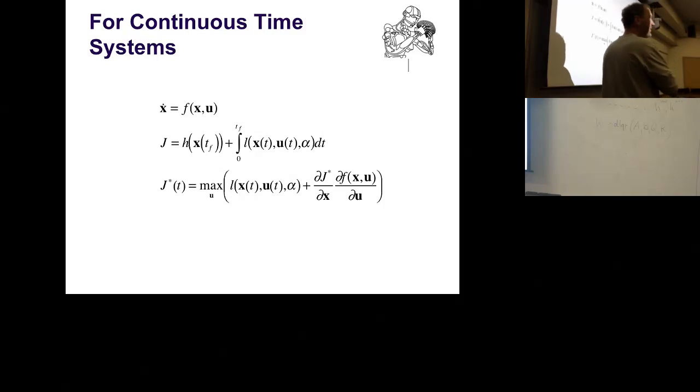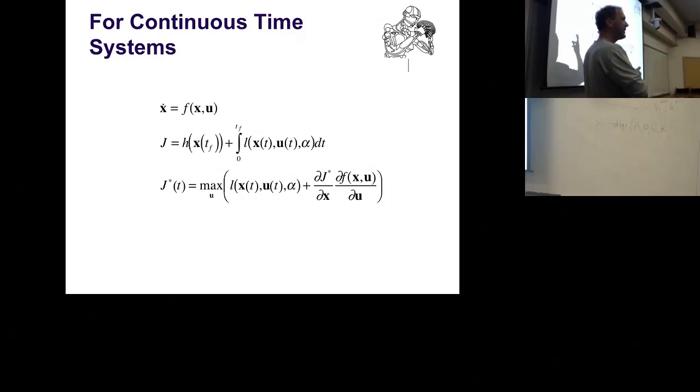Okay. People love that method. It's very important. Many people use it. It's incredibly robust. It's incredibly easy to design. MATLAB has beautiful tools to compute it. You don't even have to know anything about it. And even coding it yourself, if you see that Riccati equation, which just has to converge and get the gain, is trivial. It's really trivial. It's like 2 pages of code at most to do that. You can make it ugly and make it half a page of code. Nobody can read it, but it's good enough.